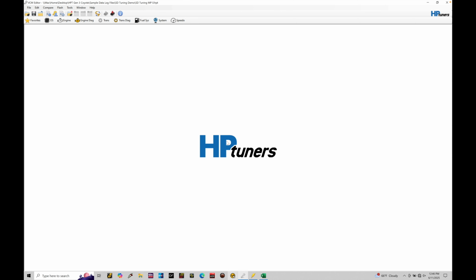So we're going to go through looking at just maybe 1, 2, maybe 3 at the max speed density calibration for different MAP points in this tutorial. I'm not going to go through all of them because the process is redundant, but it is relatively straightforward. So we need to be able to lock our MAP points here. I'll start off at MAP point 0. We'll go through, we'll drive it, we'll log it, and then we'll take our data and learn how we can use the SD calculator to update the SD tables.